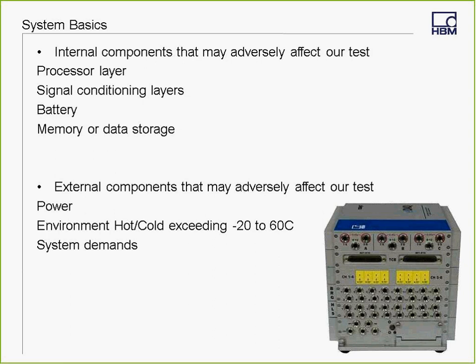Environment: the negative environment would be predominantly extreme heat or cold. Very rarely do we see problems caused by heat outside of the specification of the eDAQ. More commonly, we see startup problems caused by the eDAQ being below -20 C at startup. By system demands, we mean the test parameters and channel count that is solely up to the test engineer setting up the test. The eDAQ may or may not react well to being placed under these demands. We will discuss this later on.